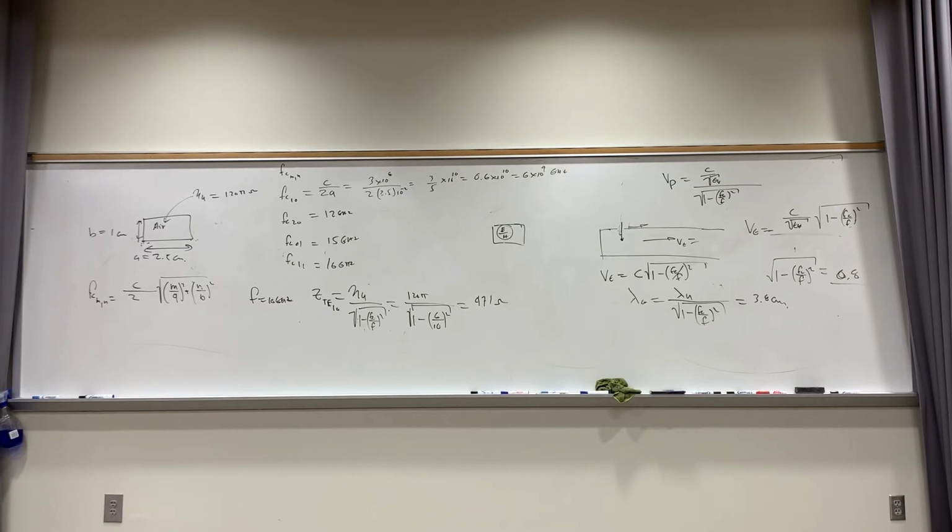The bottom line is when you have a waveguide, you want to make sure you operate it between the 10 mode and the next normal mode, which is usually the 20 mode. There's 10, 20. And you operate it about halfway between. So if it goes between 6 and say 12, you can operate 8 to 10. Higher up is better. The further away from that lower cutoff, the better it is. So around 10 gigahertz.